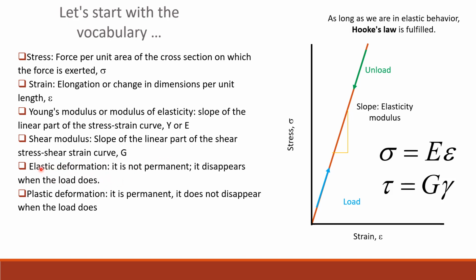Then I talk about elastic deformation. If the deformation I provoke with a load is not permanent, so it disappears as far as the load disappears. And we talk about plastic deformation when it's permanent. So when the load disappears, the deformation still is in the material, so it's not recovered.